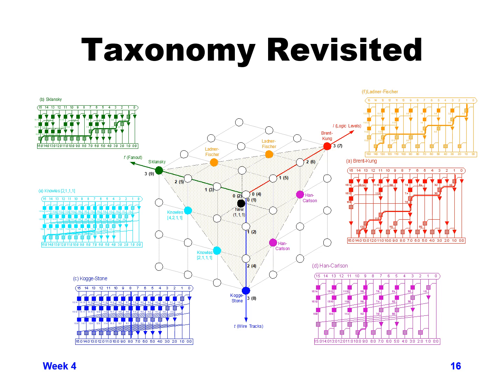The Brent-Kung design has the maximum number of logic levels but minimizing wire tracks and fan out. And Kogge-Stone is the maximum number of wire tracks and minimizing fan out and logic levels. And then you can see the other adders are the points balancing between those three outlier designs.